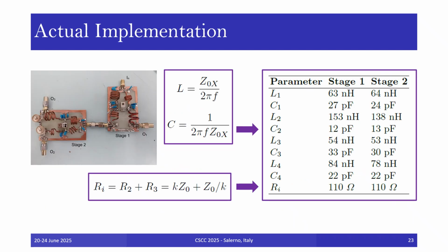In the actual implementation, the inductors were designed as high-quality factor air-cored coils using a copper wire of gauge AWG14 on a 9.5 mm format to be able to handle the 1 kW input power. Each inductor was manually designed and characterized via a one-port measurement carried out using the Siglent SVA1032X vector network analyzer to guarantee that the required inductance was achieved. The capacitors were implemented as multi-layer high-voltage ceramic capacitors with a voltage rating of 500 volts.